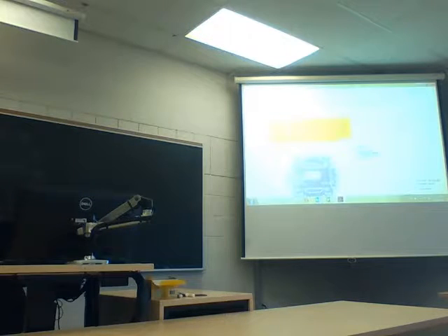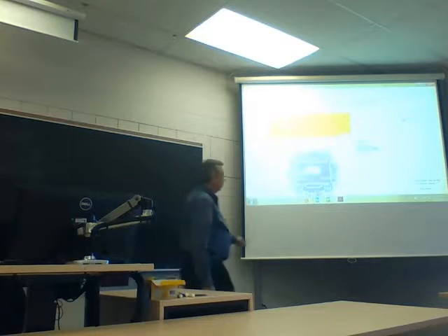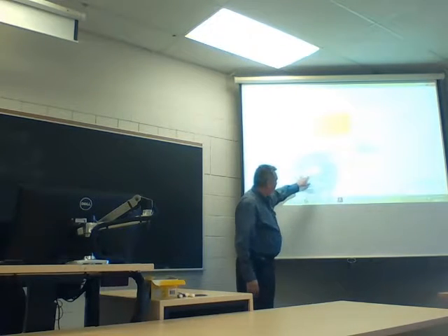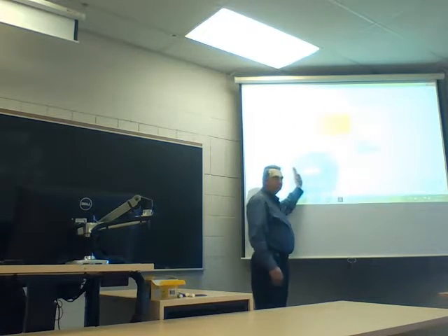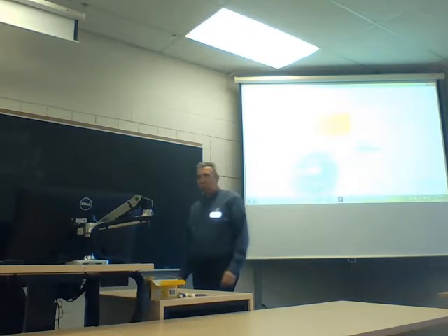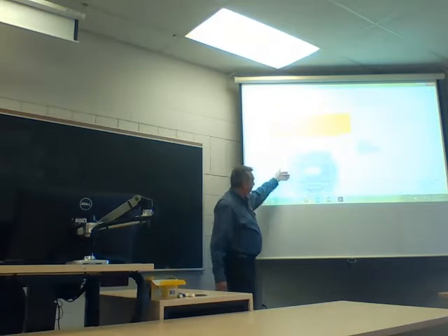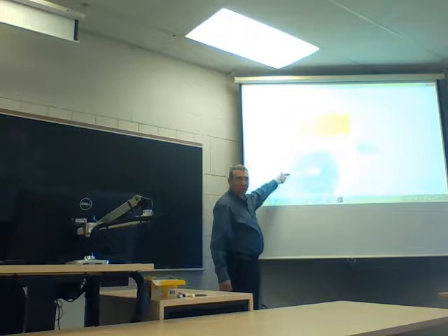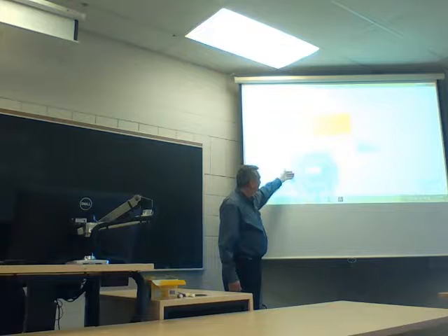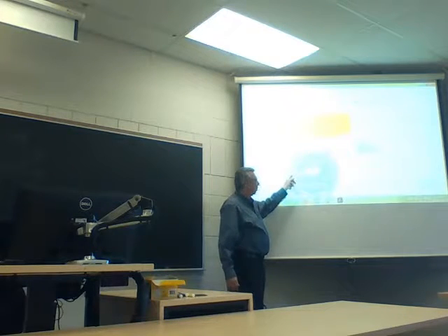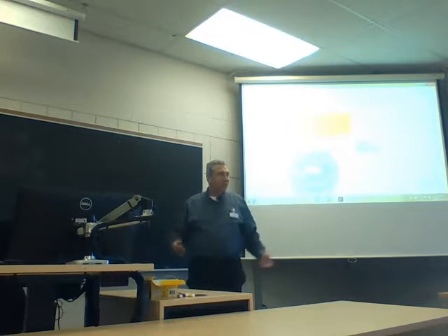Double acting is a beautiful picture. You can see we've got intake and suction and discharges, so that's the compression at each end. It compresses both ways. It's real important to make sure these seals are good. With this packing gland, with a seal there, sometimes a mechanical seal, as it comes this way, if this seal's no good, that's kind of a wasted stroke.